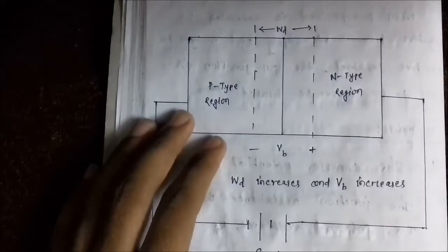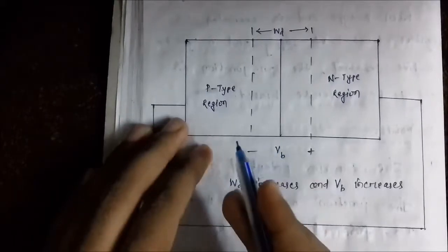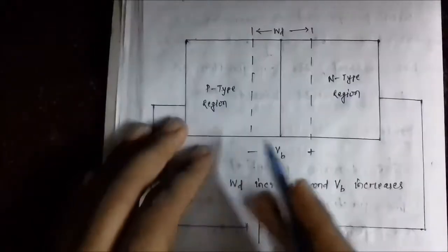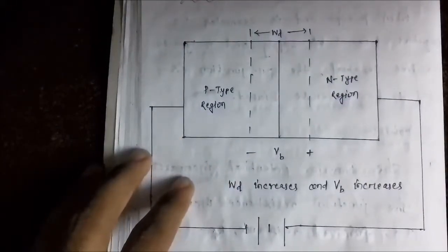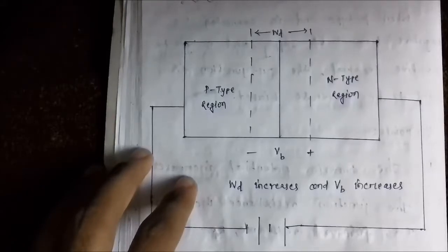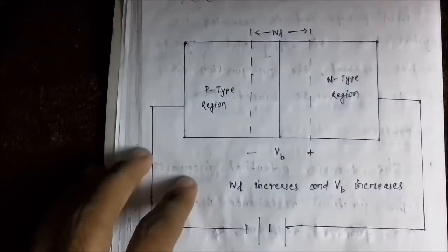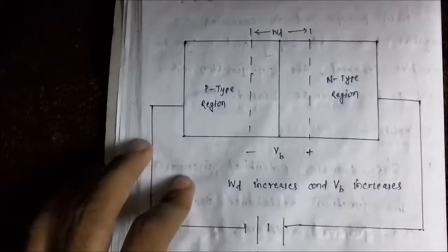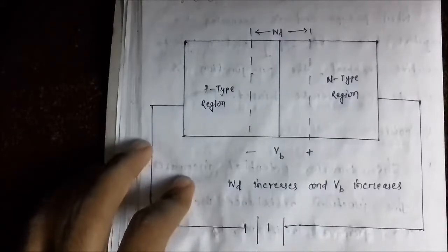So the reverse voltage at which this phenomenon takes place is called the breakdown voltage. At this voltage, a breakdown of the junction occurs, characterized by a sharp increase in current. It is due to the kinetic energy increase of the minority charge carriers, which enables them to knock out electrons by breaking the covalent bonds of the semiconductor.